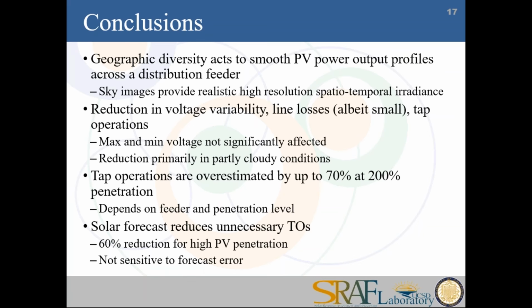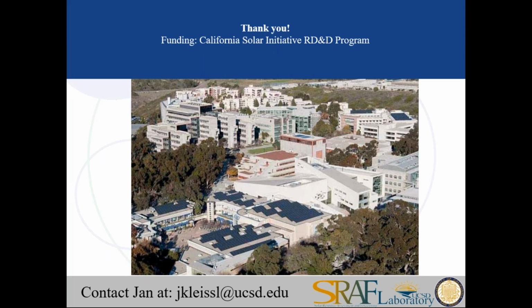I just want to point out that something we did not consider here, and that will be a major impact in the future, is the inverter reactive power control. So you can actually use the solar power inverters to also control the voltage, which we in this case did not consider.